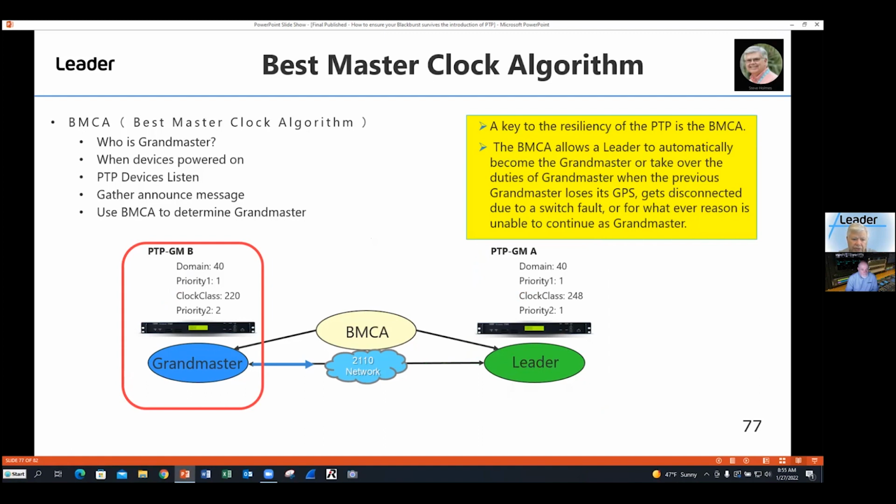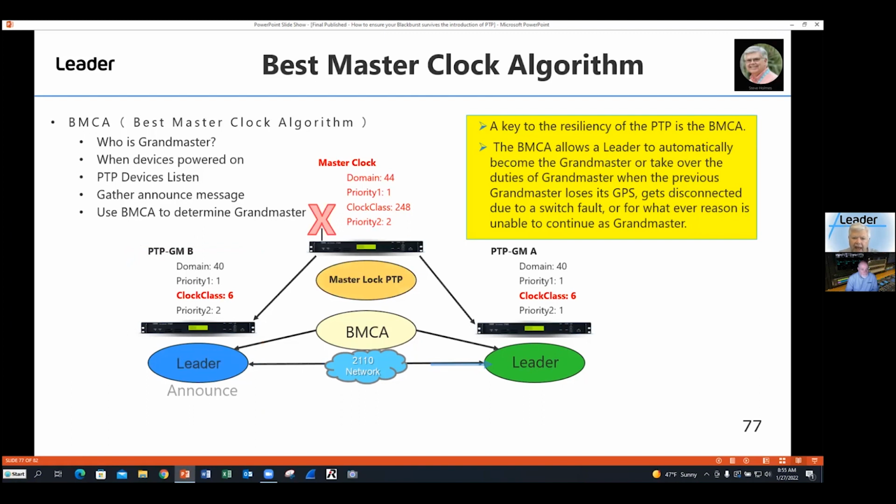The best way, as we see from the previous, would be to have a master lock source that is your clock coming from GPS, or you have this situation, and lock a third generator and then provide PTP from that generator down to the two generators on the bottom. That PTP passes the equivalent of GPS to the bottom two generators. So they're going to look like, from a clock class quality, that they are GPS locked.